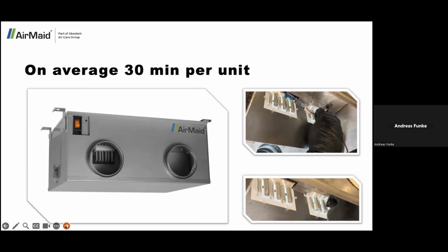Instead of the brush, you could also take a cloth with alcohol. With the cloth, you just have to be careful that you are not breaking the glasses. The glasses are very vulnerable, so we need to be careful when cleaning them. That is actually all. And if you do this at least one time a year, maybe 2 times a year, depending on the air quality passing through the generator, then you won't have any further problems with the unit.